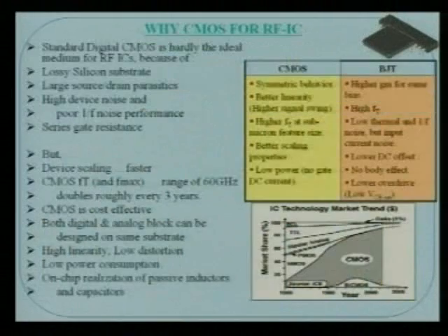That's true. Now come to the pros and cons of CMOS and the BJT. But even if you look at all the pros and cons, you find that basically the cost, area, and flexibility of the design favor CMOS. With recent technology, initially people could not think of having a 20 gigahertz fT, that is, cutoff frequency for MOS devices. But now we are going to 100 to 150 gigahertz. So with a cutoff frequency of 150, you can have an operating frequency of 10 gigahertz, 20 gigahertz oscillators.